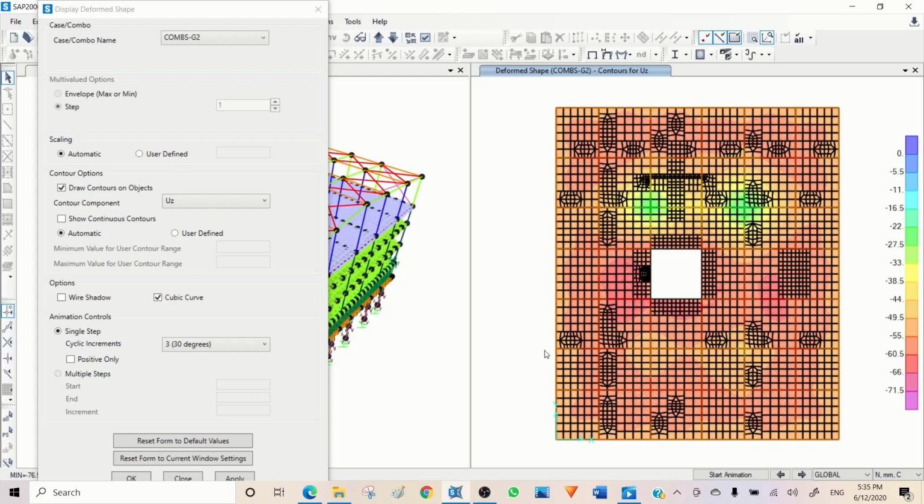Roughly in concrete, the short-term deformation you see here times 3 would be your long-term deformation. I will keep the cracked section here 0.35 and check my short-term deflection based on that. This is conservative. If you have any sophisticated software that can check all those deflections, that's perfectly fine.